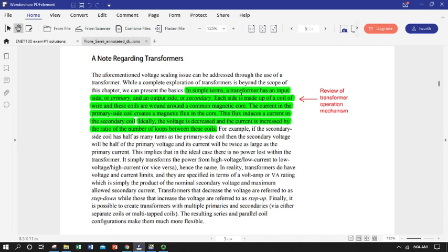So that's our sinusoidal voltage supply in this case. It's the secondary of a transformer. And of course the number of coils in our primary versus our secondary is what determines the voltage ratio between the two. So we can have step up or step down. So that's what we are using for our input.